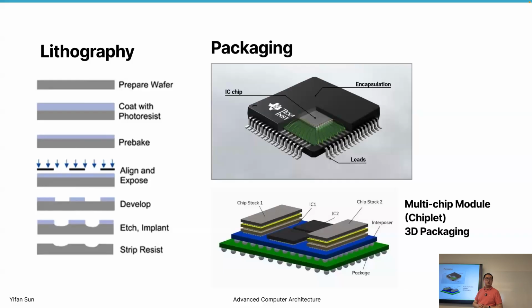So is this the same thing as the system on a chip? No, system on chip is basically where you have different modules, different IP cores. What are IP cores? For example, Wi-Fi module, memory controller. Those are different IP cores, or CPU cores, GPU cores, accelerators. Those things are integrated into one circuit. That's an SoC, system on chip. So a chip is not only about the CPU, it's everything. So that's system on chip.